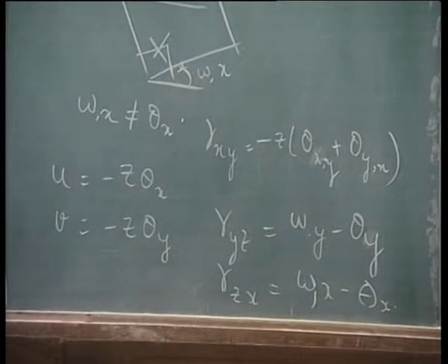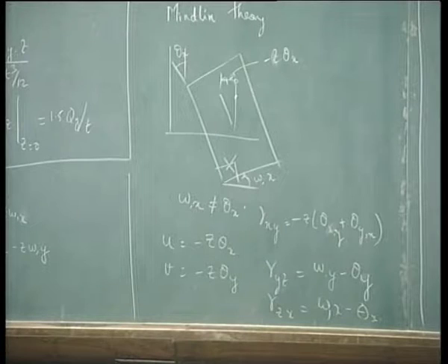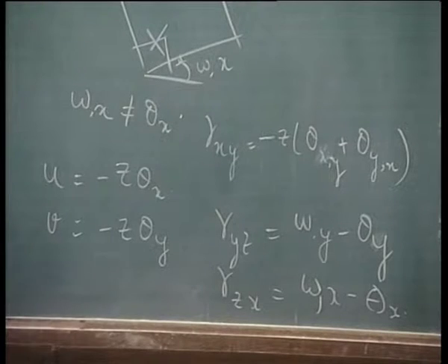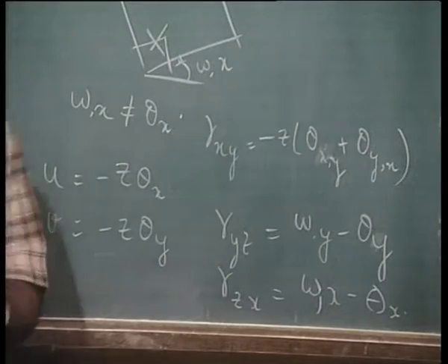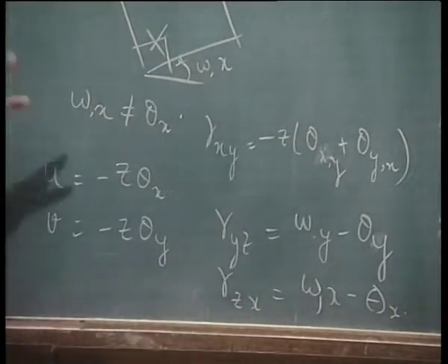So what is the result of this formulation or assumption? We do not have only 3 moments, Mx, My and Mxy. We also have the shear forces taken into account, Qx and Qy, through the shear strains and hence the shear stresses and so on. In other words, what is the next step that we require? Of course, we require the stress strain relationship.